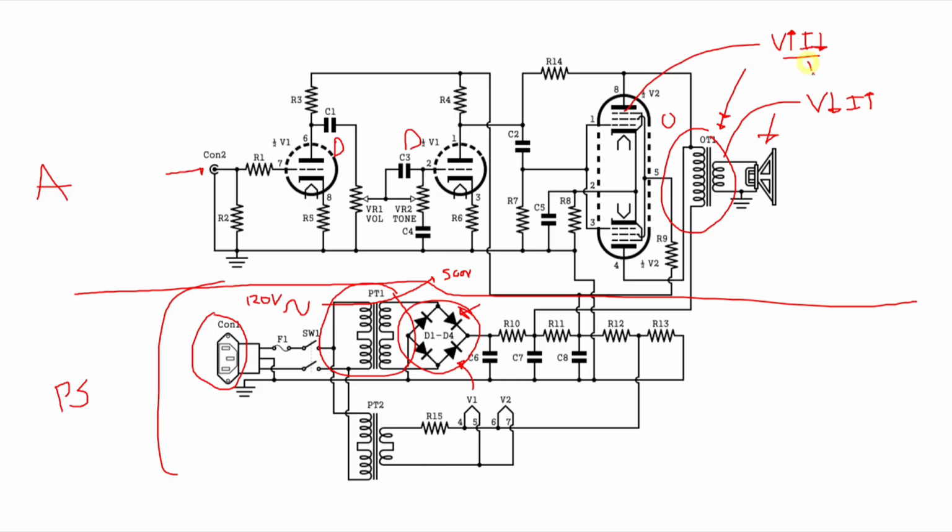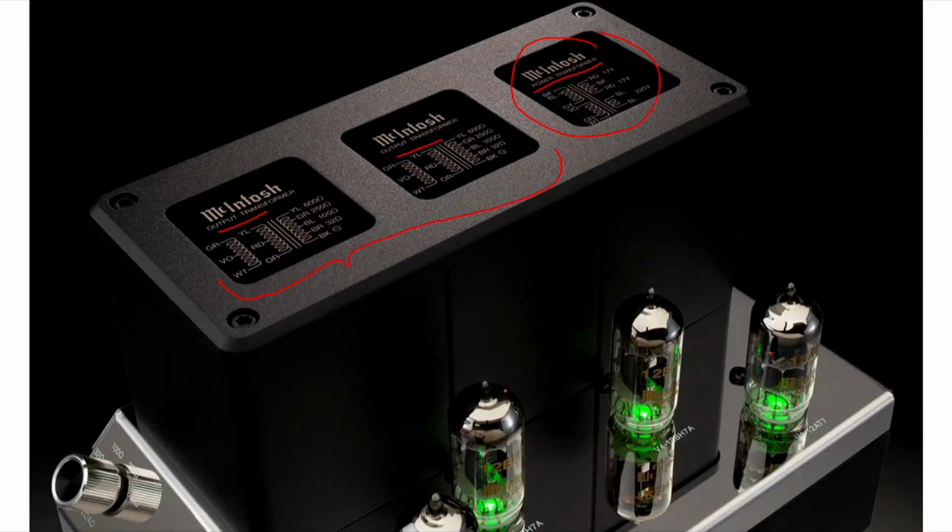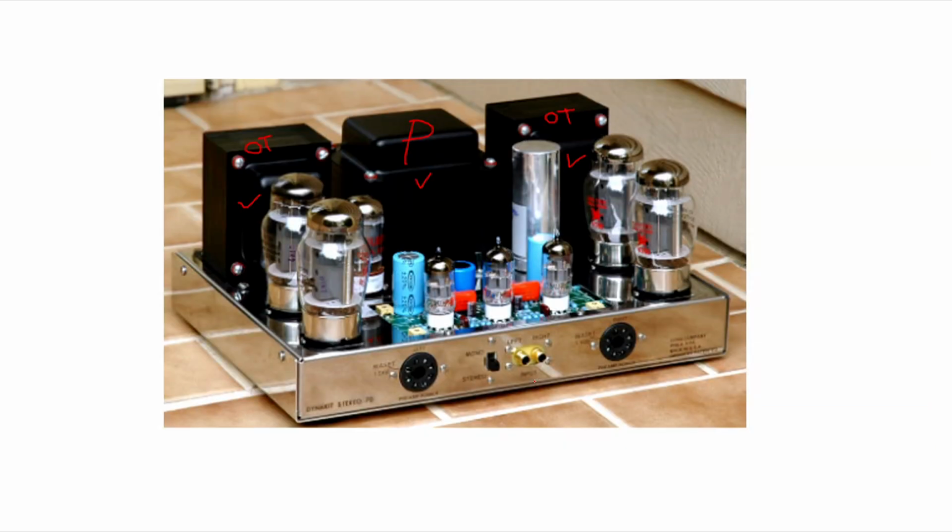The power remains the same. So to drive our speaker, we need a lower voltage, but we need a higher current. And through that process, we do something called impedance matching. Now, I'm not going to get into that now. But the point being is the output transformer's function, while similar, is fundamentally different than the power transformer. And let's leave it at that now. We'll get into more of that later.